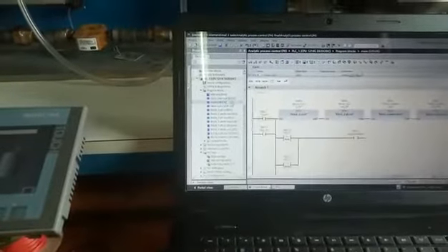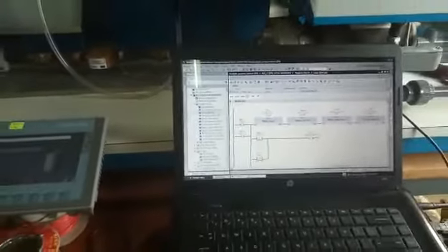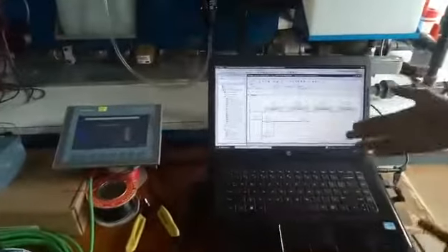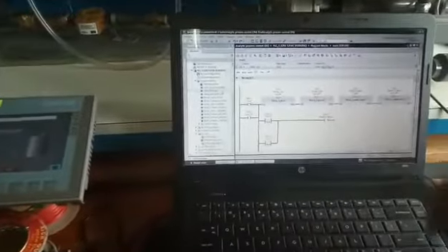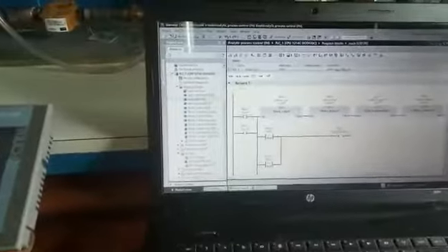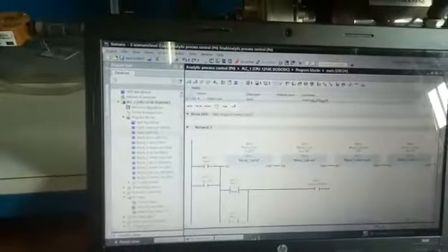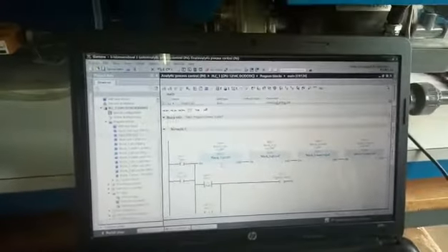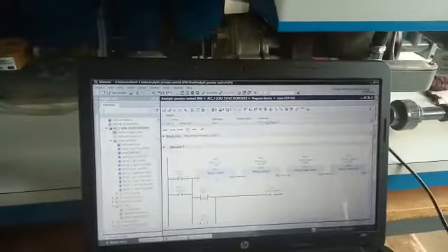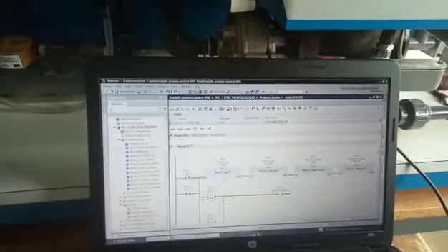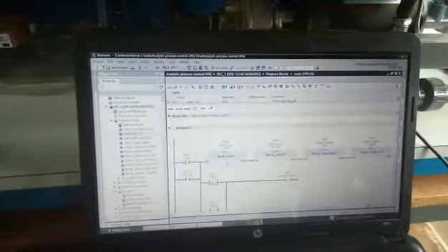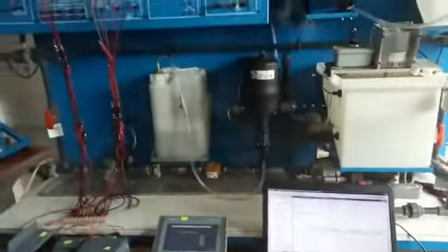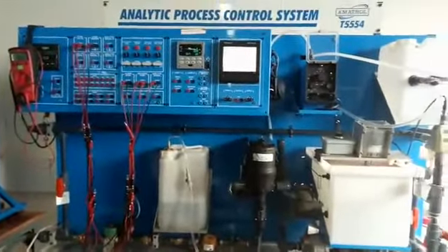Then I'll go to the main function block. The main function block is composed of the whole cluster of our program. It contains both the function blocks and also incorporates actuators such as the agitator motor, circulation pump, alarm, and a couple of tags. The function blocks are both for the input and output for the pH and the water level. Basically, what we do in the function block is scale or normalize the values you get from the pH sensor and the pressure sensor at certain ranges, such as the analytic signal at 4 to 20, to get basic outputs that are used in the program.